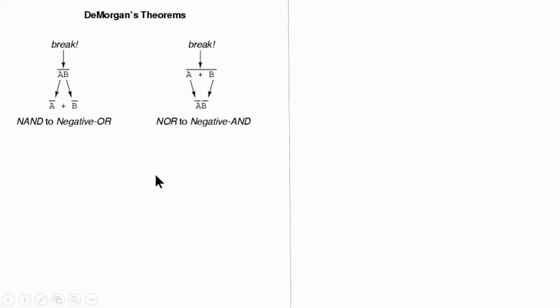Again, breaking down DeMorgan's theorem graphically, visually, you can imagine something like this. You have A and B, the complement of the product A and B. So how does it work? You break this long bar and sum it. That's how you can imagine it, and it's easy to understand DeMorgan's law graphically like this. If you have the complement of A B, you break the long bar in the middle and you add them, and this is equivalent to this.